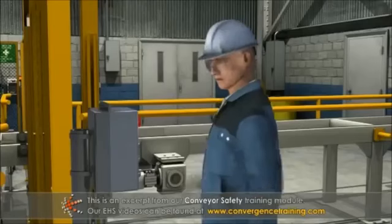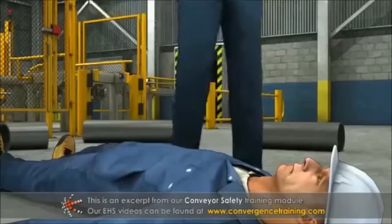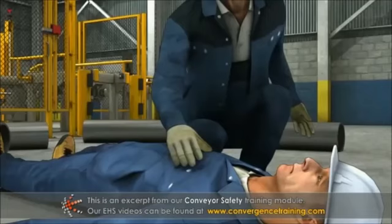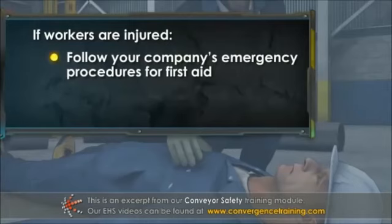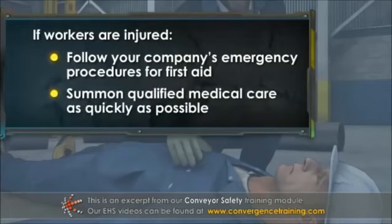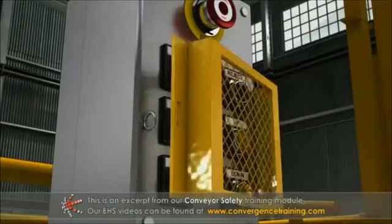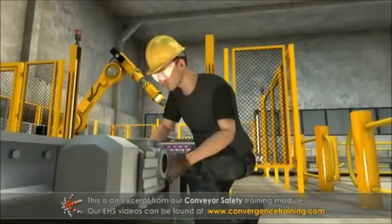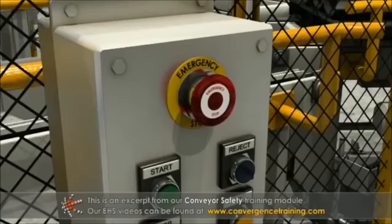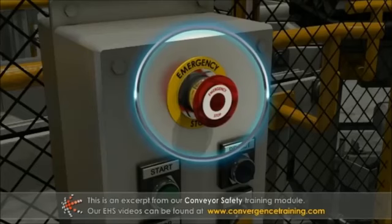When an emergency stop has been activated, the conveyor should stop immediately. Once the conveyor is stopped, then the emergency situation can be dealt with. If workers are injured, follow your company's emergency procedures for first aid, or summon qualified medical care as quickly as possible. Immediately following any emergency, the conveyor should be locked out and tagged out. The conveyor should then be inspected to identify the cause of the stoppage and be corrected before it is restarted. Before the conveyor is restarted, the e-stop may need to be reset to its normal operating position.